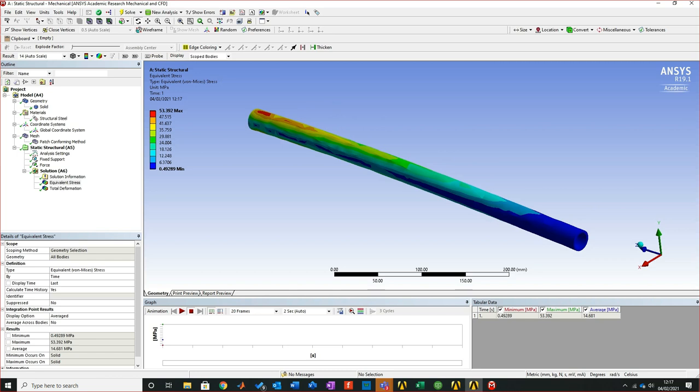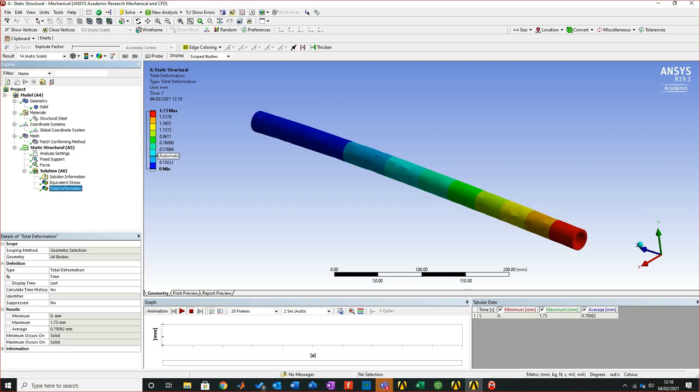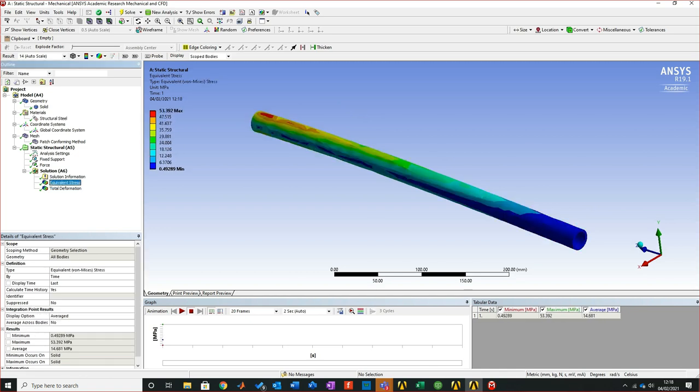Just because one person wanted to look the bee's knees, it's actually put a lot of people's lives at risk, or health at risk, I should say, which is much more important. So with this, it looks dead straightforward, but it is lethal. Now, luckily in this one, it did the automatic selection, which is a swine. But you can see there that even the deflection is totally wrong, and the stress is totally wrong. But it gives you a result that you could present and go, yeah, this is me, and it's just wrong.